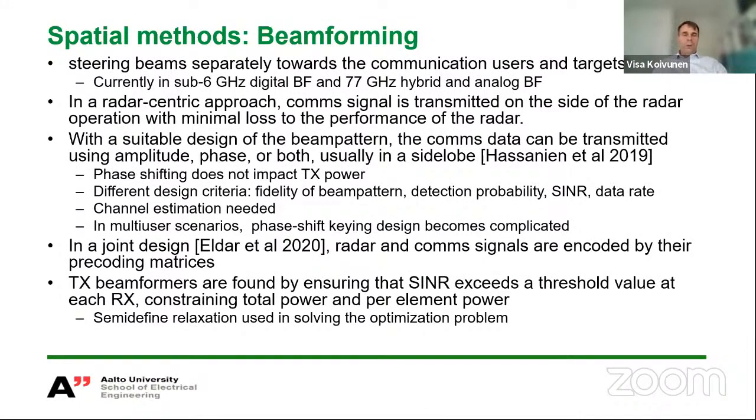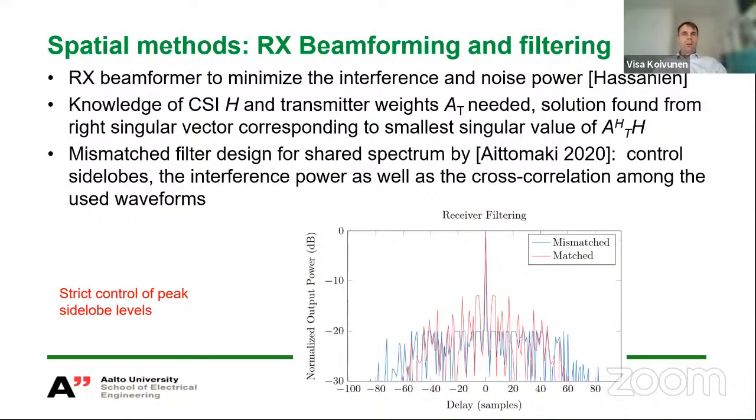Again, you end up with an optimization problem that may be solved by using semi-definite relaxation. There are a number of different designs, and one additional design I would like to point out is, instead of using a matched filter at the receiver, you could use a mismatched filter design in the shared spectrum scenarios. This is designed by Tuomas Aittamäki, where you control the side lobe level, the integrated side lobe levels, and instead